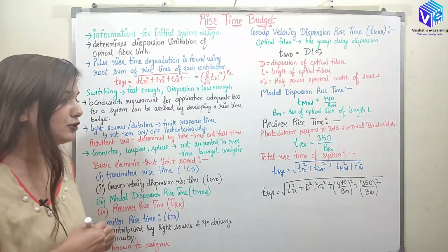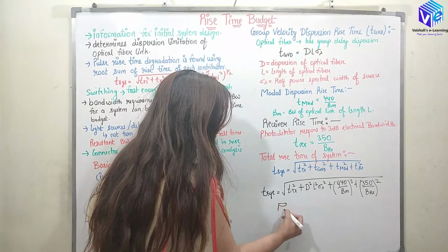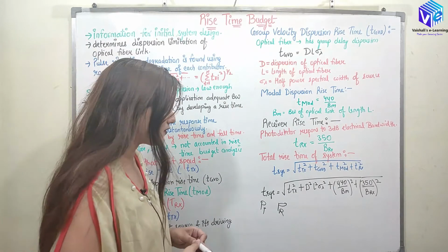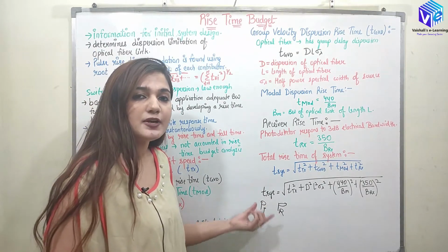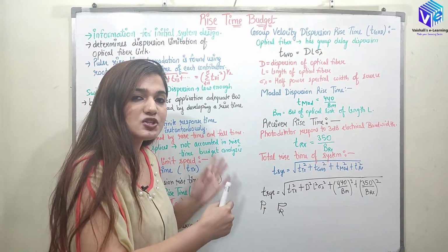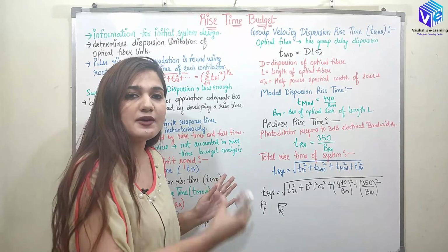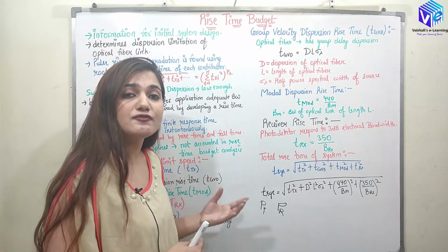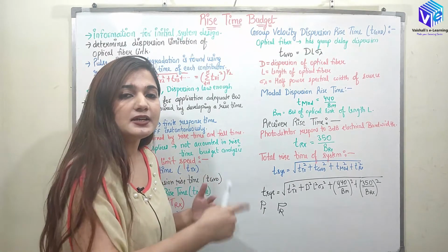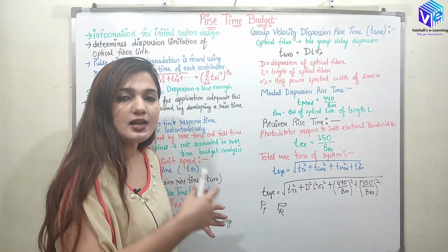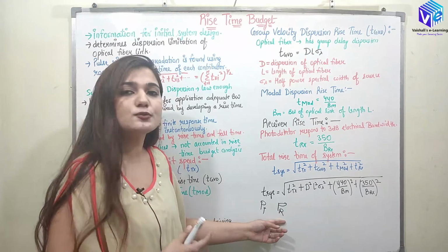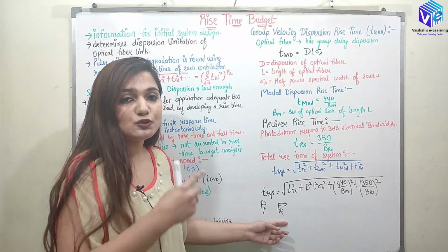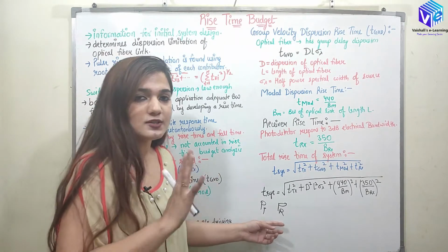Right, in the power budget, I told you how much power was sent to the receiver from the transmitter. So PR and PT were known and we knew what was the noise margin. How much power we need for transmission from transmitter to the receiver and how much power is required for the receiver to operate. And this is how we calculate what is the power we have to give to the transmitter, so that it can compensate the power losses in the channel and also the losses occurring at the receiver, and the receiver will be responding actively towards this input. Right? So this was the power budget analysis.